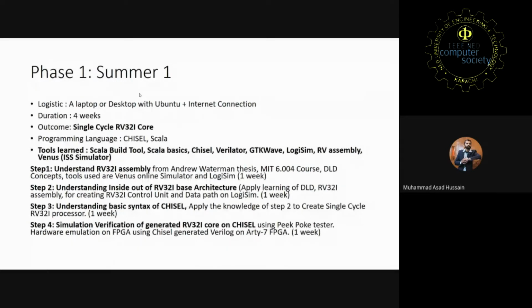Then you understand the basic syntax of Chisel. Once you have completed these two steps, you have fully developed the understanding of RV32I. You will learn the Chisel basics, and after that you will design in Chisel the RV32I data path that you created in Logisim. Verification is done using the PeekPokeTester, and for hardware emulation you can do it on an FPGA using the Chisel generated Verilog.